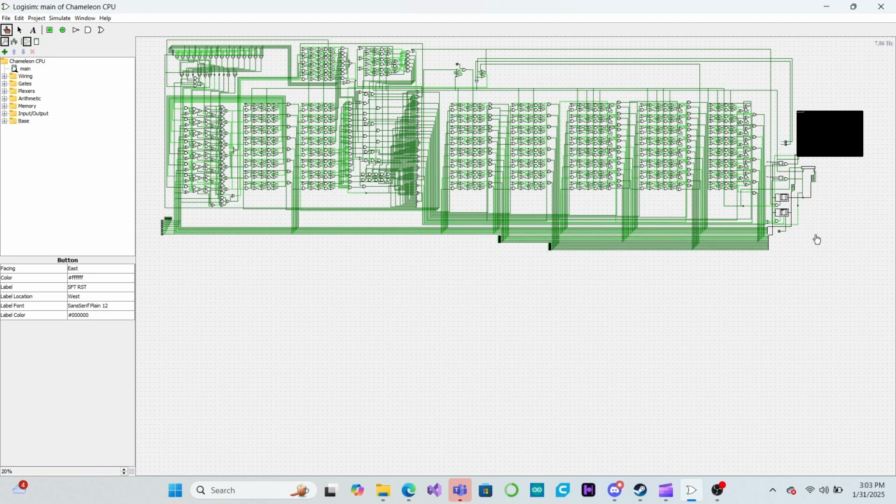Now that we know how binary addition works, we can build a circuit called an adder. We will start by building what is known as a half adder, which takes two 1-bit numbers and adds them together. Before we start putting down logic gates, let's build a truth table for our circuit. This is simply a table that lists all possible combinations of input values and what the outputs should be for those inputs. We want our half adder to take two inputs, A and B.